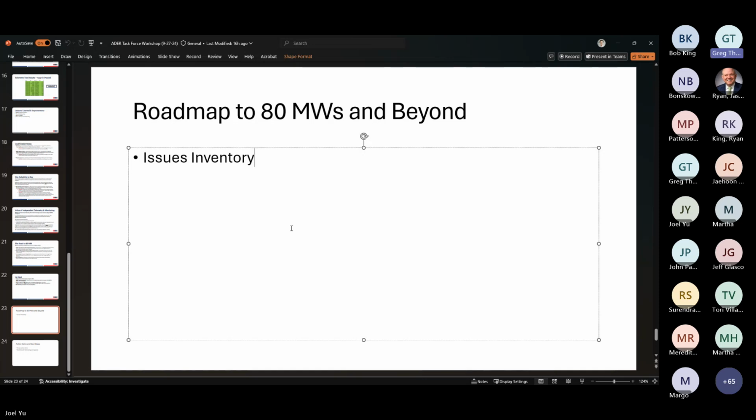And on the traditional wholesale providers of primary frequency response, we assess that capability in arrears. Said a different way, if there's a primary frequency response, it's seen on a meter, and that meter demonstrates that during a frequency event on the grid, the provider of that service fulfilled their obligations. And when we put that assessment in arrears, not only do we rely less upon more real-time data points, but we also get a faster than SCED response. Primary frequency response is on the time horizon of 2 seconds.